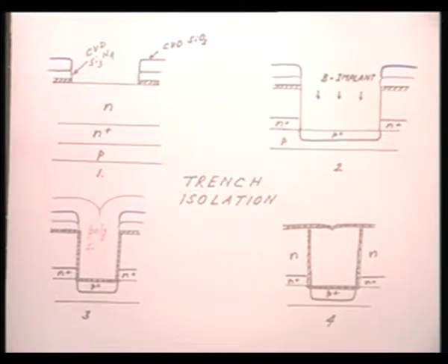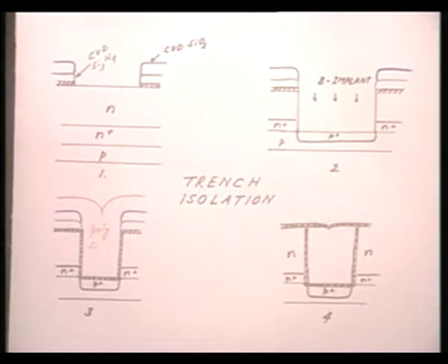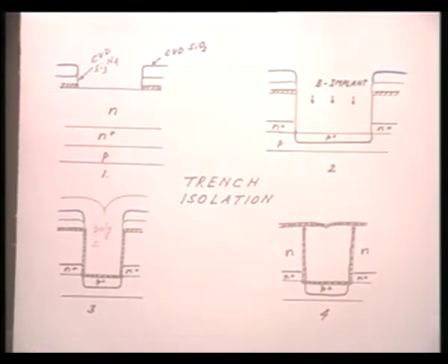So we have to have dry etching with a lot of directionality so that we can obtain an etch profile with perfectly vertical sidewall, and that is a very crucial step in trench isolation, to obtain an etch profile with perfectly vertical sidewalls, right.